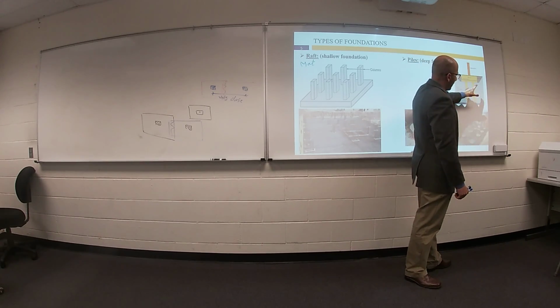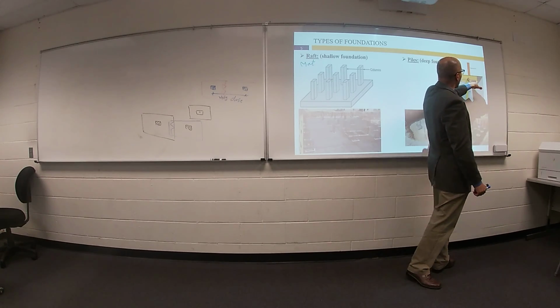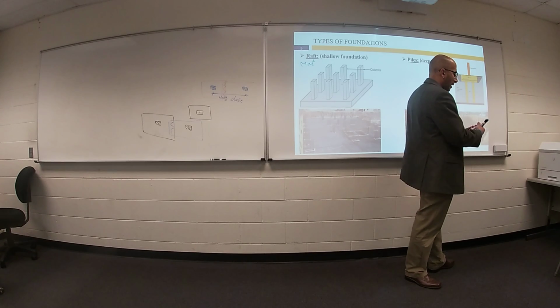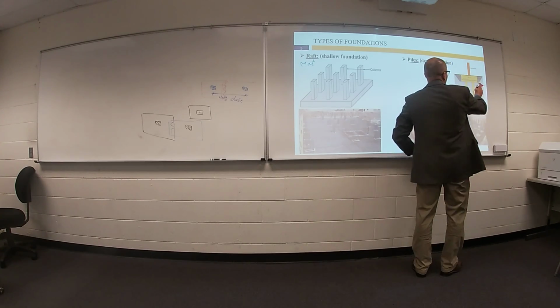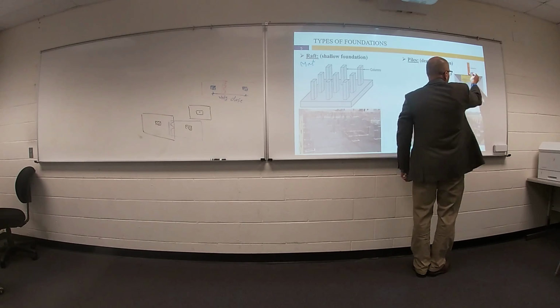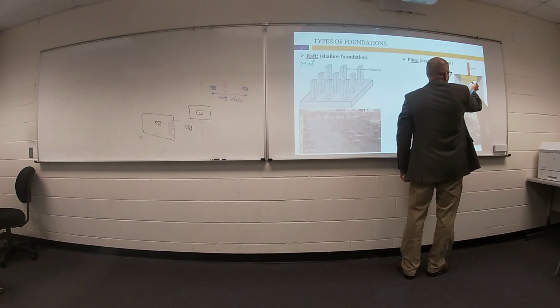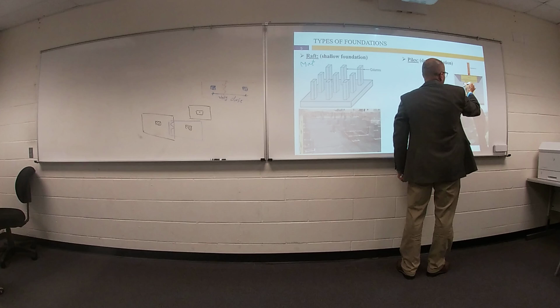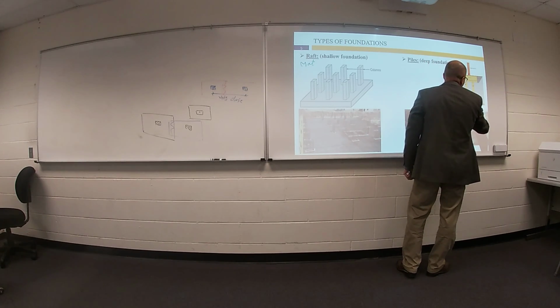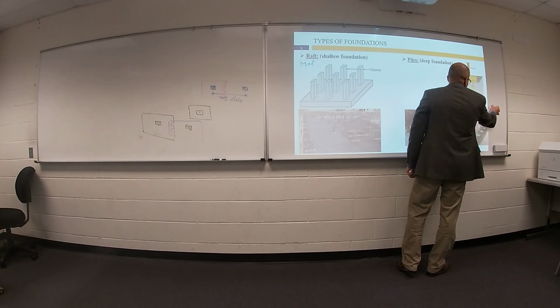This column is connected to a footing, but this time we call it a pile cap, and your pile cap is connected to the column. The strategy for piles: here is the reaction of the column. This reaction will transfer to these piles. These piles are embedded in the soil to transfer load to a very, very strong soil layer.